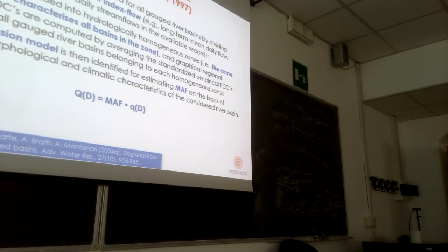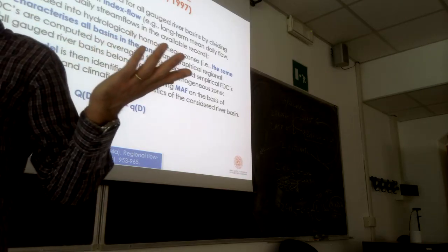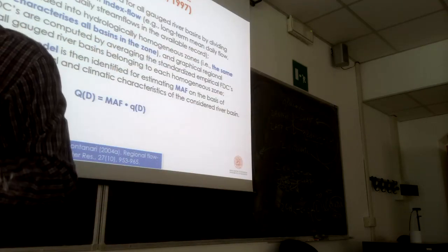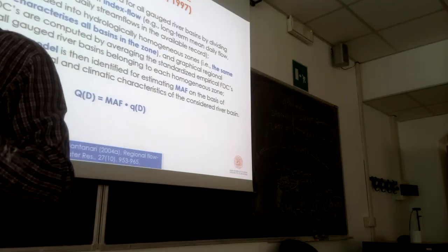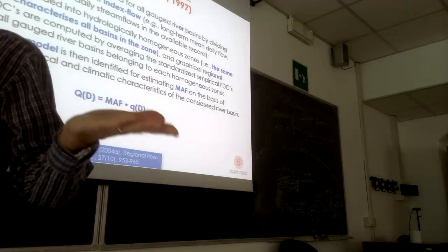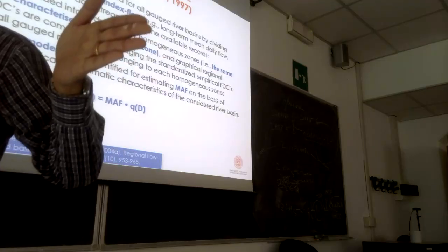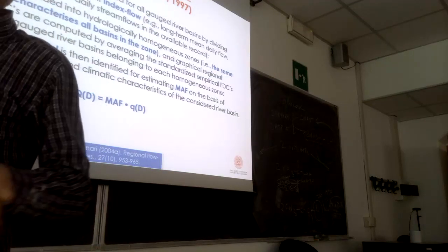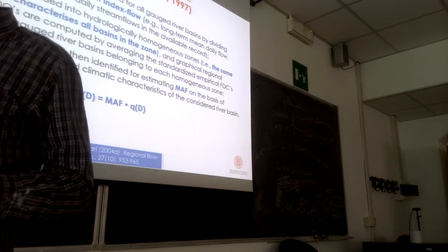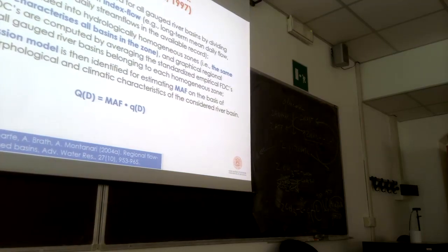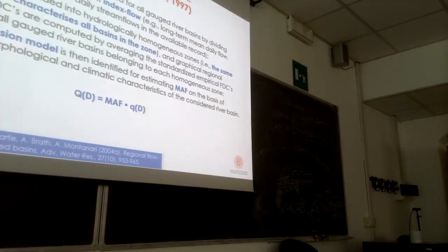If the years are 10 in a given river cross-section, I have thousands of observations of daily stream flow. So it is also referred to in the literature as a graphical regional model. It's mostly non-parametric. It doesn't use mathematical formulation to represent the duration. It's solely based on observation.